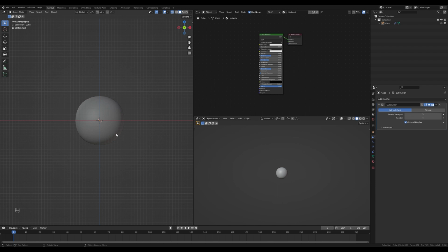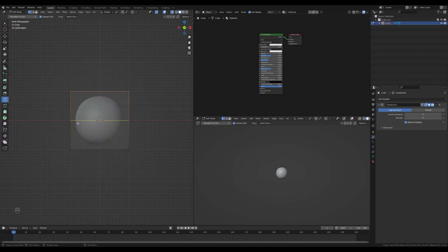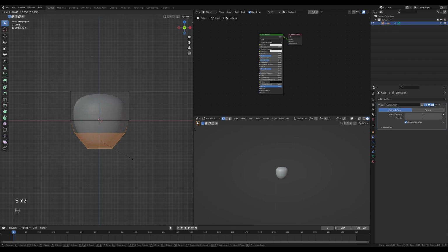Now we can add in extra vertices to add refined control anywhere we want. I like to do that with the Loop Cut tool, and if you just find the spot you're wanting to add onto, then just click and it will add vertices all around the cube. Loop Cuts will default to the center, but you can also click and drag to place it wherever you would like. Now we can add extra definition in this area and give our little guy more character. Play around with scaling and moving vertices to find the head shape you're looking for. I try to stay in orthographic mode and move and scale vertices on the same plane to keep it symmetrical.